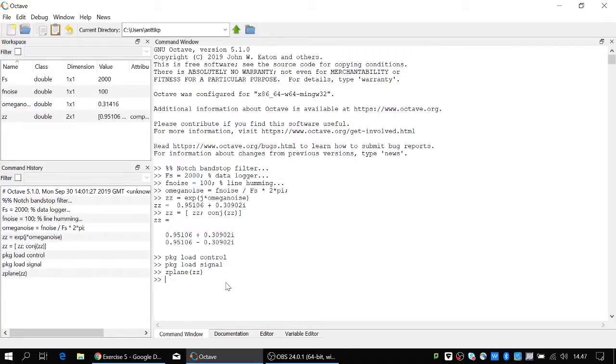What is on my minus 3 dB half width. I've just set it up. So how wide a filter would we like to have? Maybe we don't want more than, say, 20 hertz both sides. If you start having wider, then you start losing some information. And again, this is not science. It's application-specific engineering.